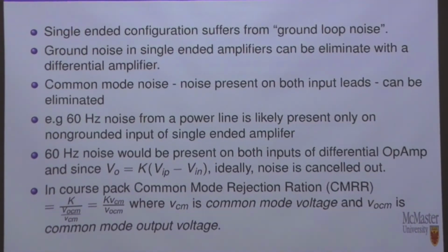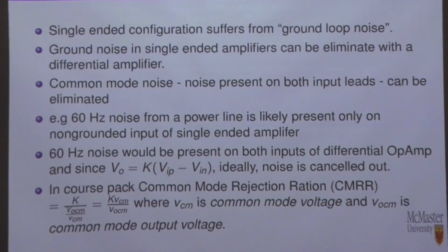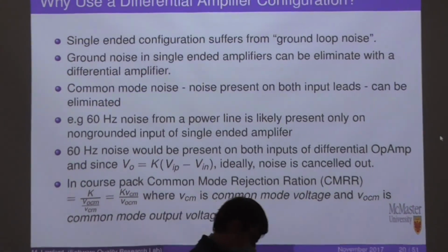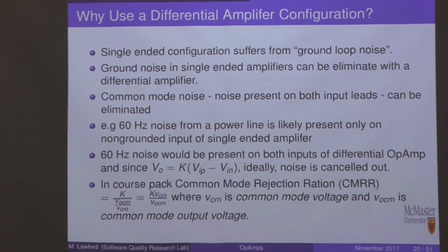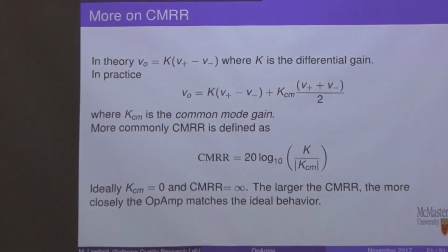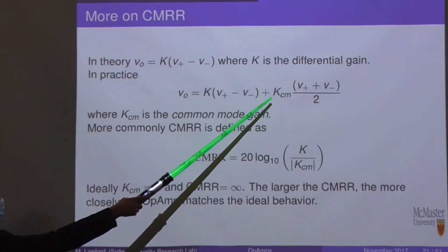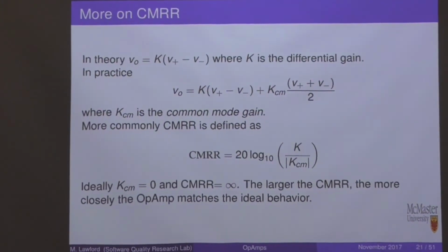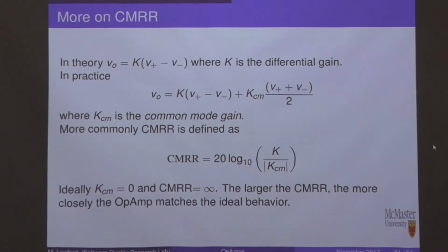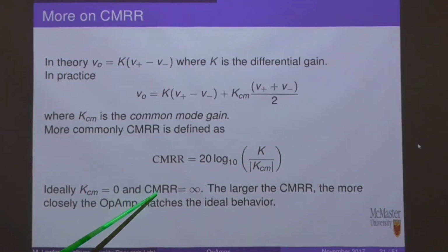It turns out that the gain that you experience from an operational amplifier is not just the gain you want, but also this other common mode term, right? So what we want, ideally, is an operational amplifier which has a high degree of common mode rejection.